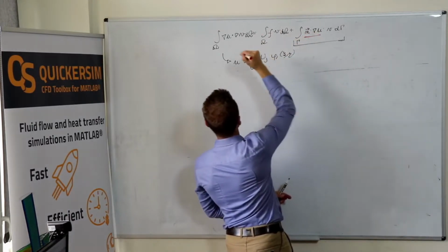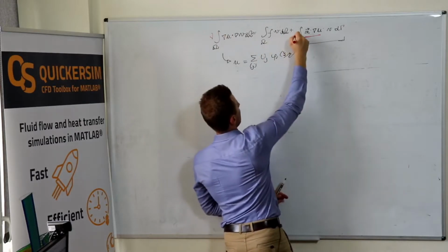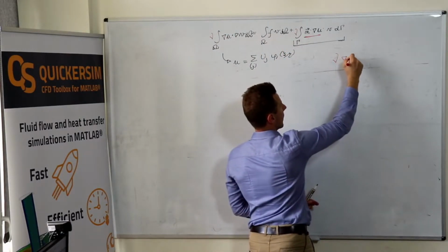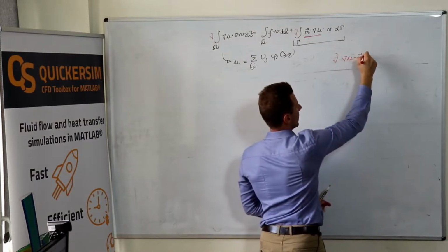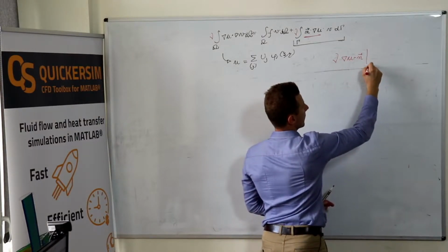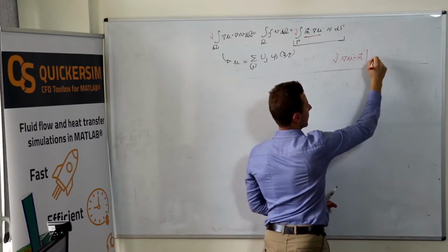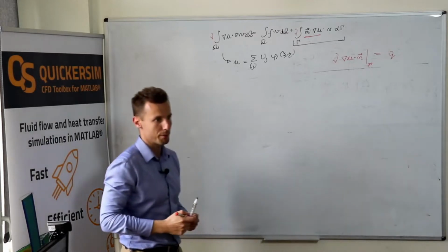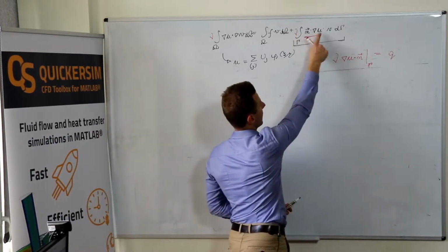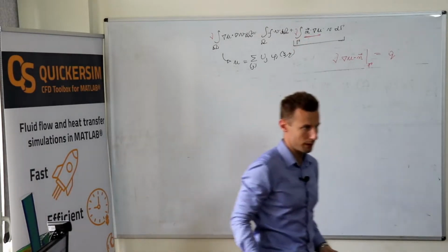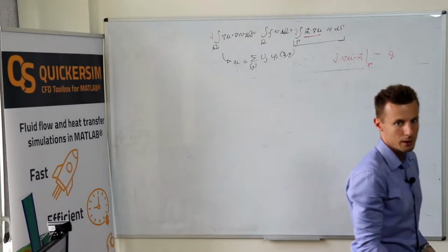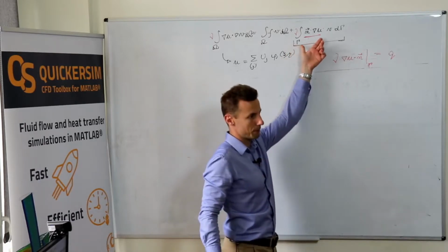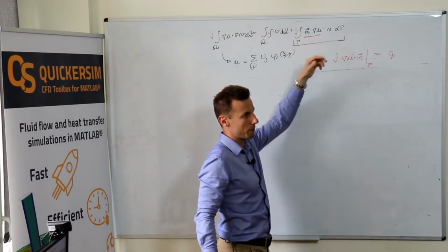Calculating something like that at the boundary means some flux at the boundary, and exactly the same naturally appears in the weak form. So it's a natural way to implement the Neumann boundary condition.